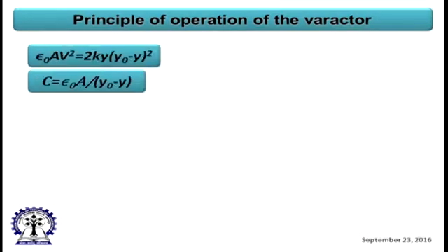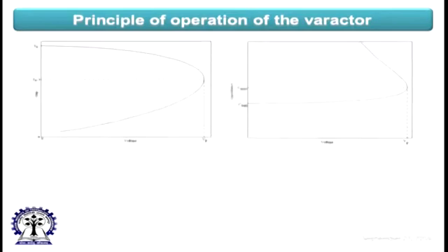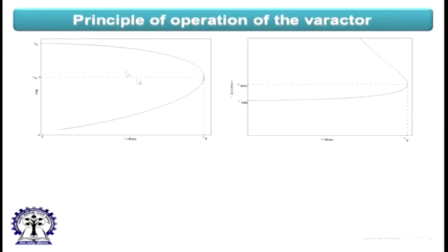So once you make that one, this is the frequency tuning characteristics. I found that you cannot increase the voltage of your varactor beyond a limit, like here VTH is the maximum limit. In this parallel plate capacitor, the maximum limit is the pull-in voltage. If you apply the voltage beyond that, then the top plate will actually collapse on the bottom plate. That is called the pull-in phenomenon.